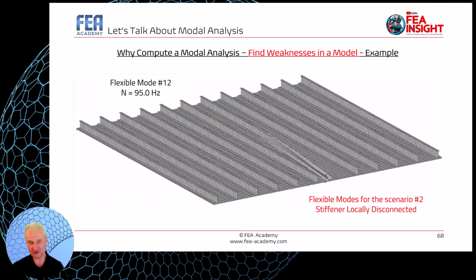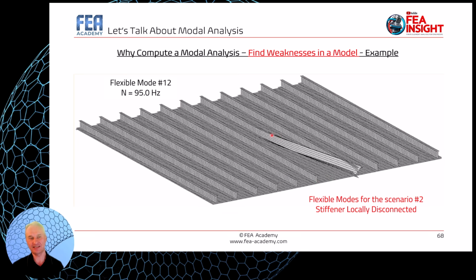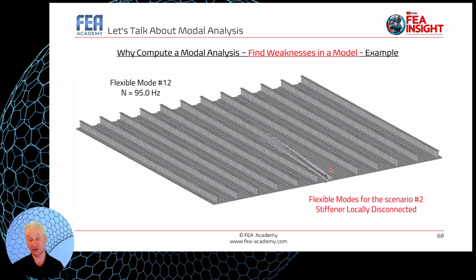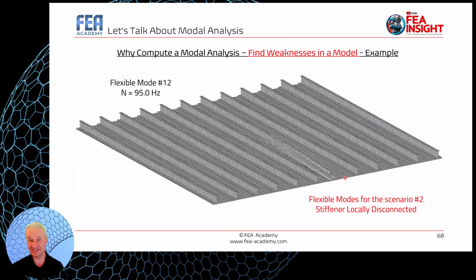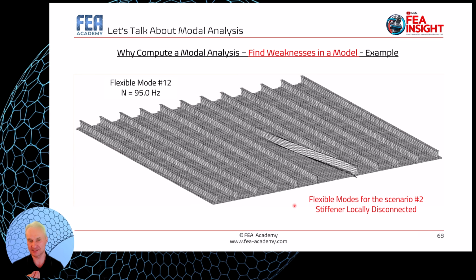We see that on mode 10 also. You see, in mode 10, this one is working alone, not together, sorry. It's clearly obvious that this stiffener is not attached to the panel just by looking at the mode shape associated with the natural frequency.